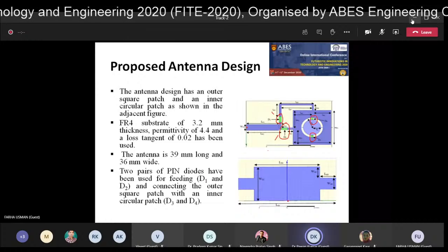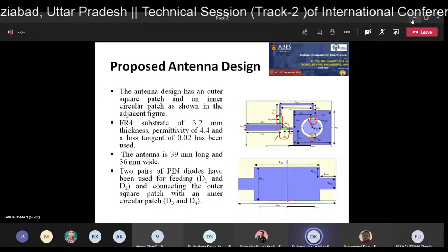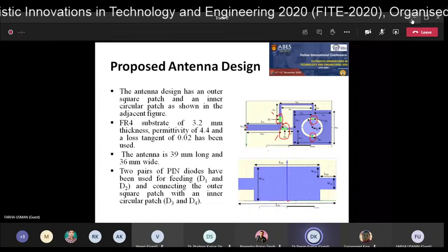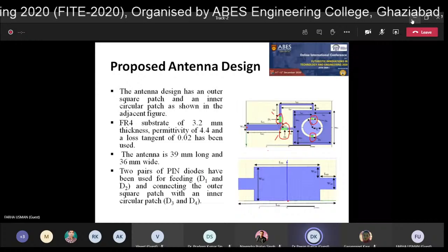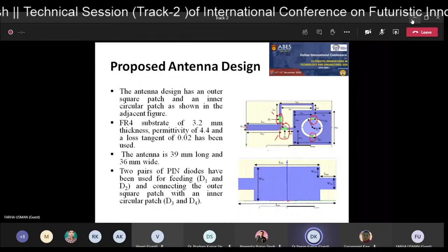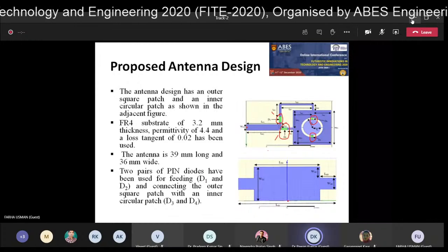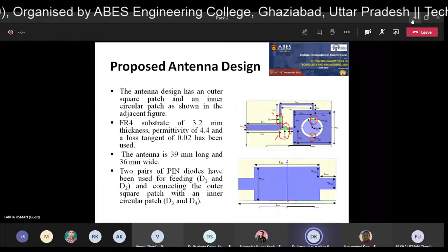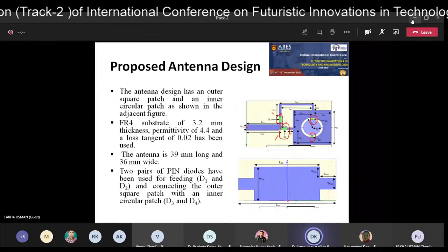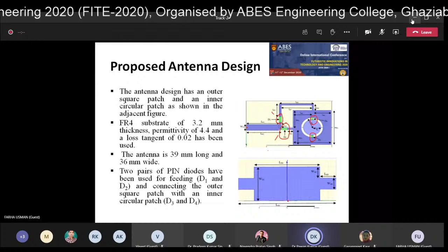You performed the simulation only? No algorithm has been developed to find out the optimal sizing of the reconfiguration in the antenna? In the simulation there is a part that we can use to achieve the optimum value of the antenna size. It gives the option of optimizing the results, the size, and the parameters. These are inbuilt features of that software. What software did you use? It is ANSOFT HFSS, that is High Frequency Structure Simulator version 13.